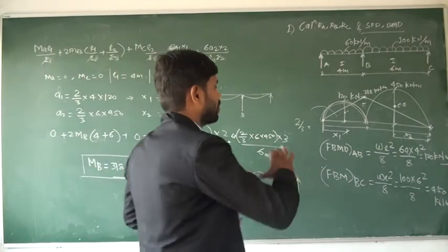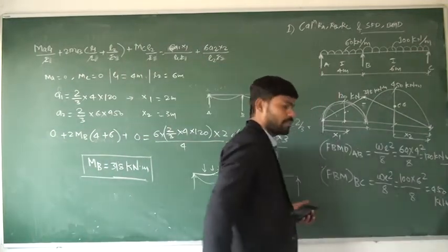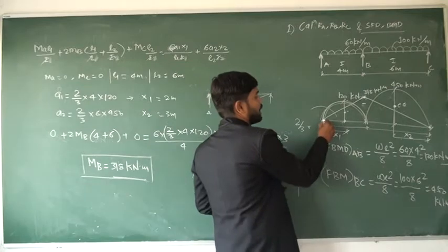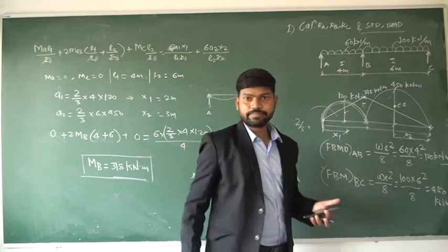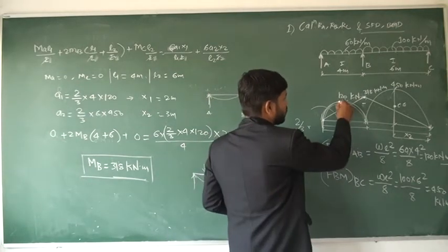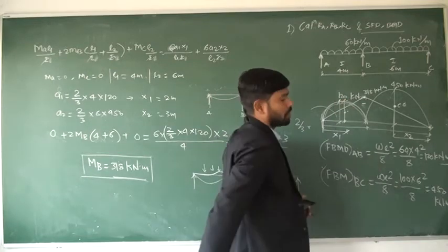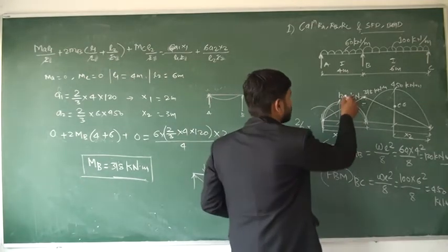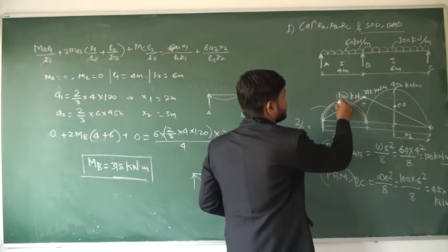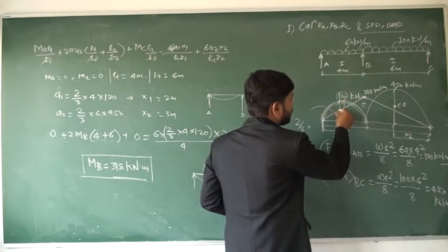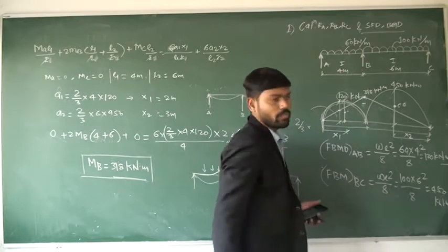This is called a resultant bending moment diagram, which predicts the actual condition of bending moment in the beam. Okay, so now if you try to read this diagram, see bending moment at this location is 0. But at the center, if you calculate the bending moment, here this 120 is the free bending moment and this is the support negative bending moment.